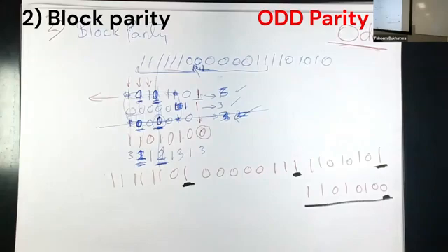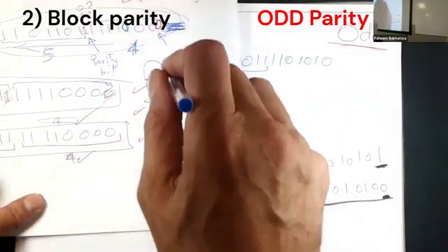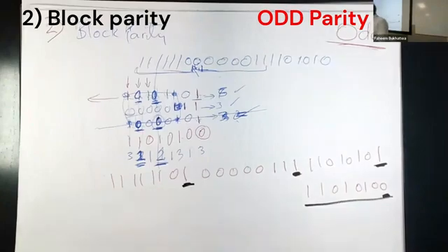It doesn't easily happen that you only get those 4 bits. Normally, if you get some noise, you get a few bits together in the same byte, or maybe the next, those 2 bytes. It's very unusual that you get those exact 4 bits. So it performs much better from an error discovering capabilities. It discovers a lot more errors, and it's the same speed and almost the same redundant data. So this is a big improvement to the parity error detection system.